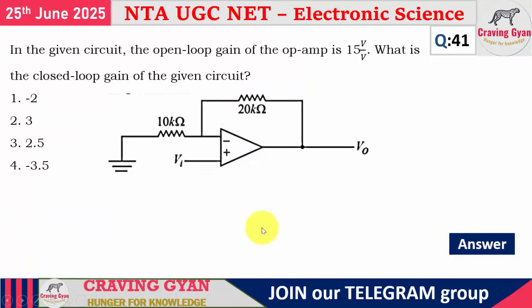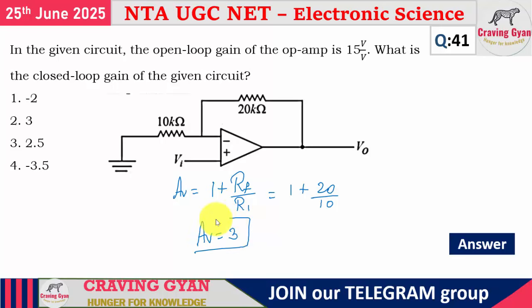Important. Now this question, try to comment your answer in the comment section. Based on how those fellows have solved, I am going to teach you. Look at the things. This is a non-inverting configuration. In the case of non-inverting configuration, what will be the value of gain? Gain equals 1 plus RF divided by R1, which equals 1 plus 20K divided by 10K, which equals 1 plus 2, that is 3. So the gain will be equal to 3.